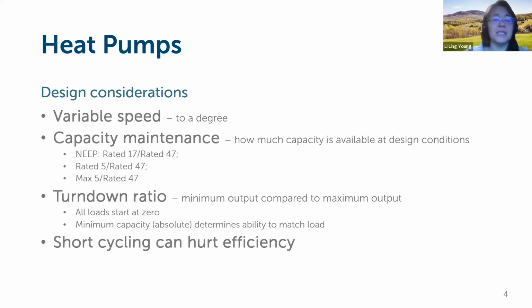Okay, so capacity maintenance is a question of what we think of as the capacity of the heat pump. How well do we hold on to that capacity as we get into the colder temperatures? And of course, this is very important in this climate, but in other climates, it's not as important. But when we're considering which heat pump to select, a lot of people will look at capacity maintenance and say, I want a heat pump that will maintain 80% of its capacity, or 90, or 100% of its capacity at some lower temperature, at 5 degrees, or at -5 degrees, or at my design temperature in the area where I'm designing for. The problem with capacity maintenance is that there's all these different ways of calculating it.